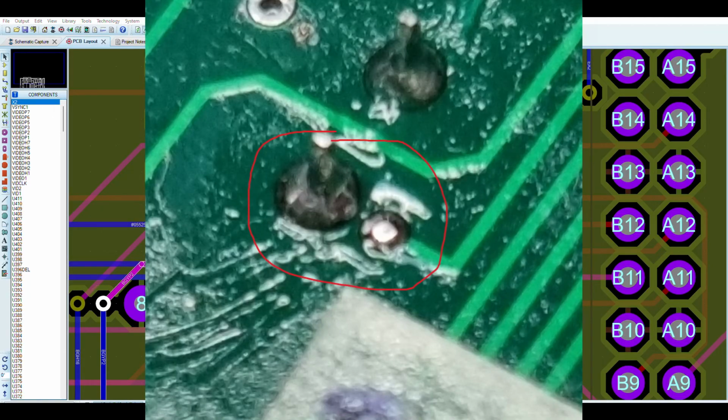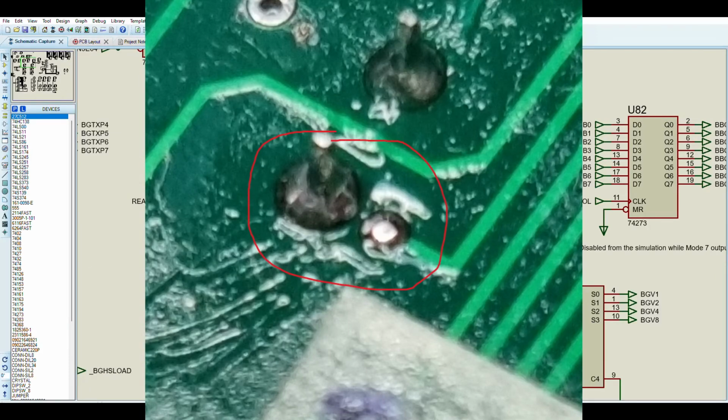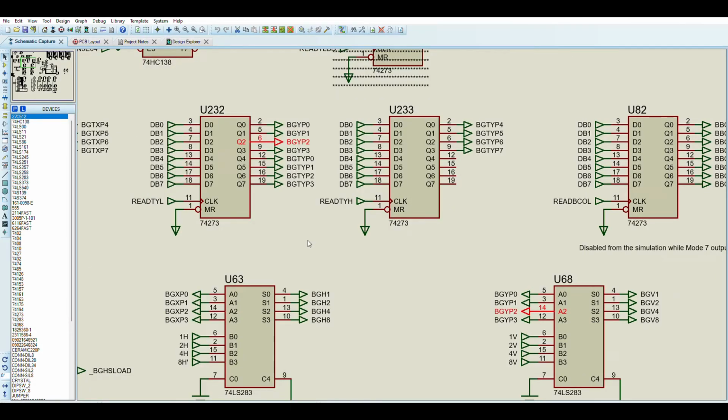So if I highlight the net on the schematic, we can see here that the register for one of the Y positions, the net comes from here, which is P2, and it comes in here, which is the adder for the vertical position, plus the lower 4 bits of the scroll position, and then outputting the final lower 4 bits of the real virtual screen position to actually look up all of the data.